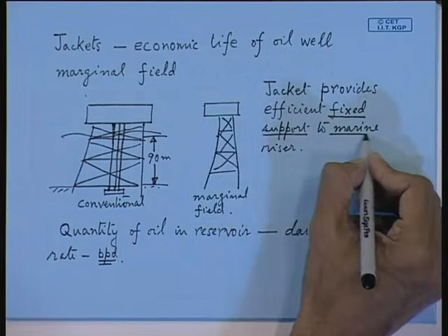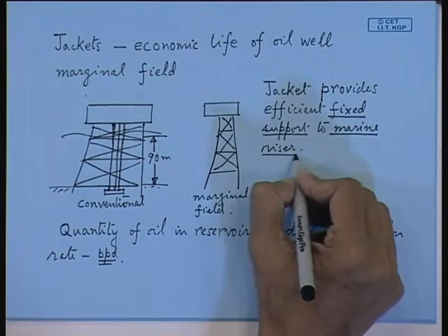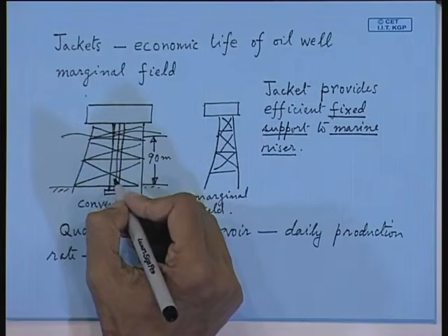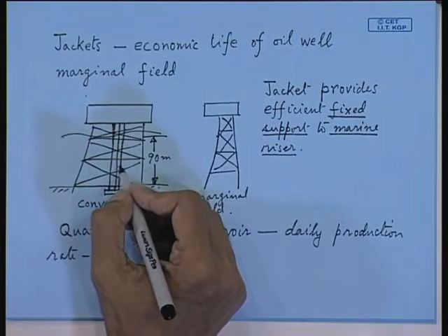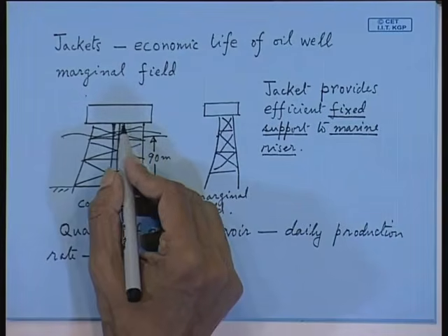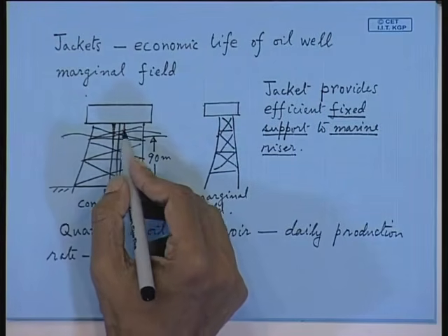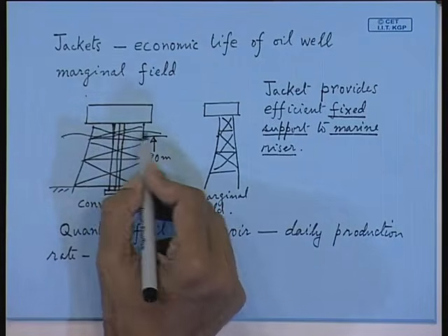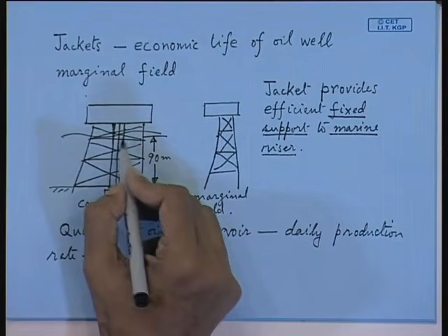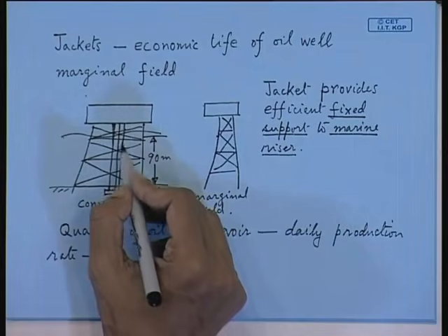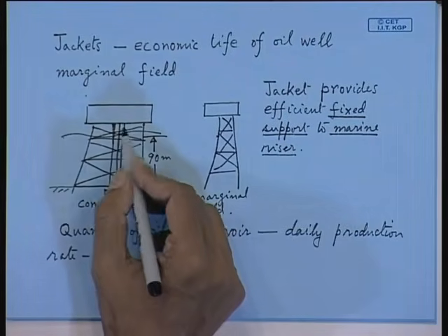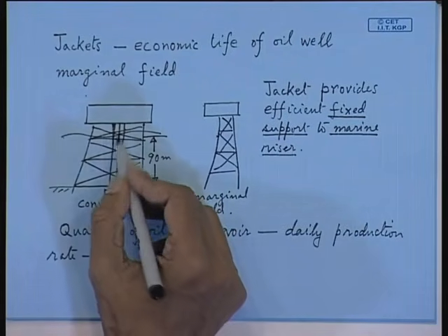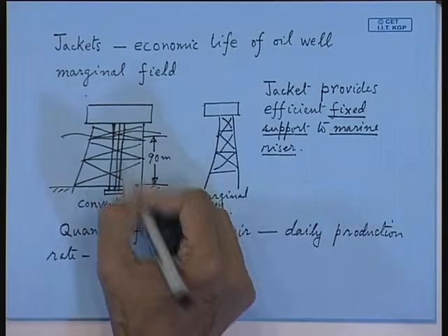So, if you have more number of supports, that means it will resist the bending moment on the pipe. Because of the wave load, you will find there is a large bending moment coming onto these pipes. If you give some number of support points or more, the failure of the pipeline due to bending will be less.